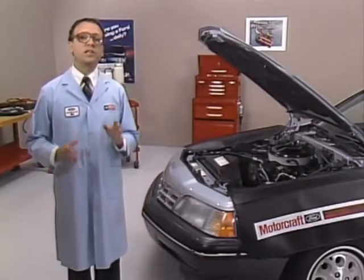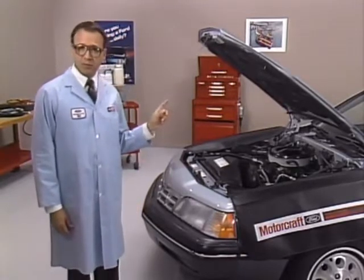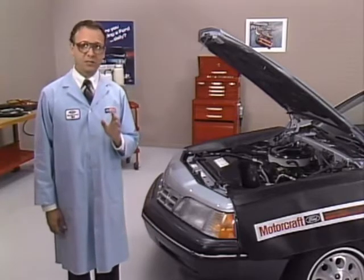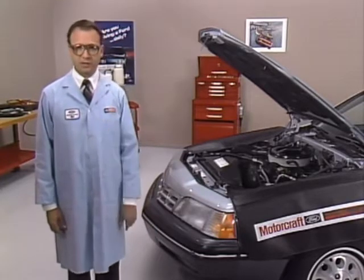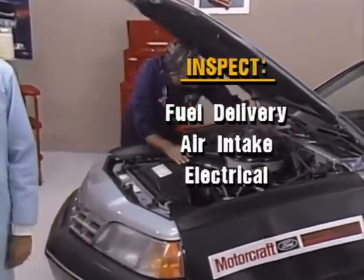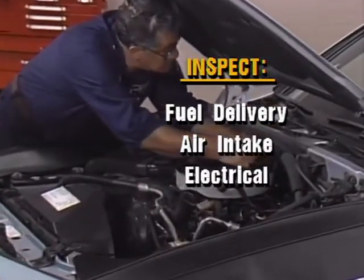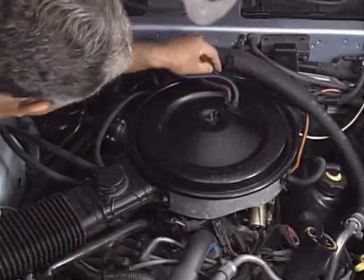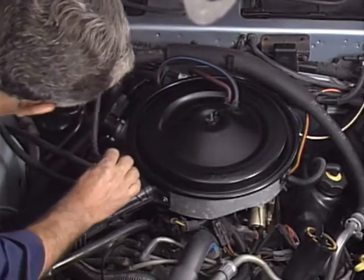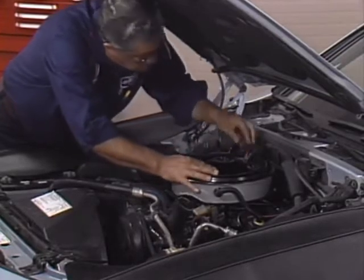Now let's take a look at a central fuel injection system. This is a 3.8-liter high-pressure CFI engine. Most inspections for CFI systems are about the same as for multi-point systems. You have to inspect the fuel delivery, air intake, and electrical components, both in the engine compartment and under the vehicle. However, on some high-pressure CFI systems, make sure that the vacuum hoses for the heated air intake system are securely connected and in good condition.